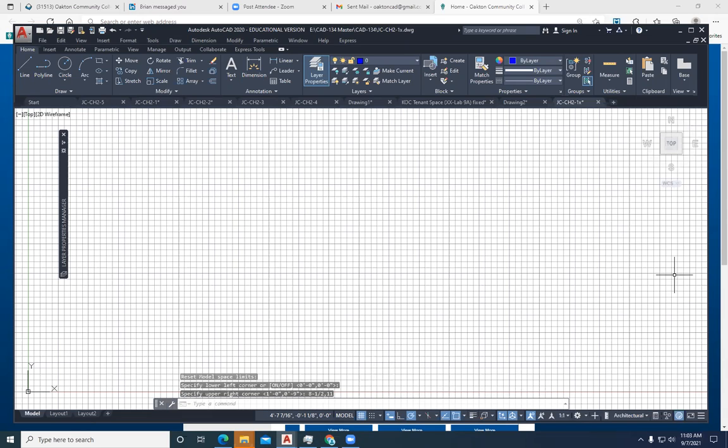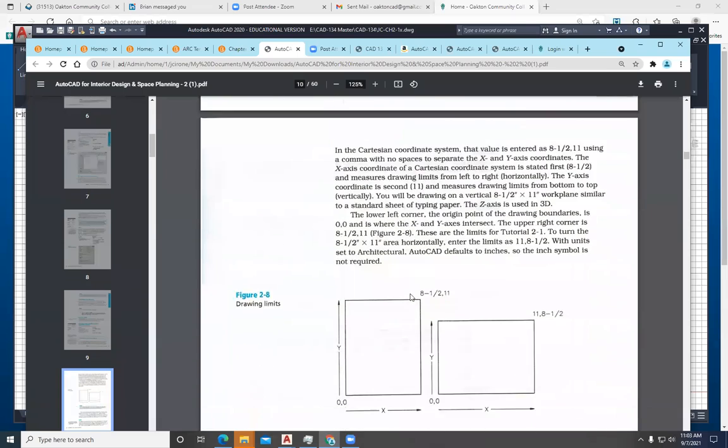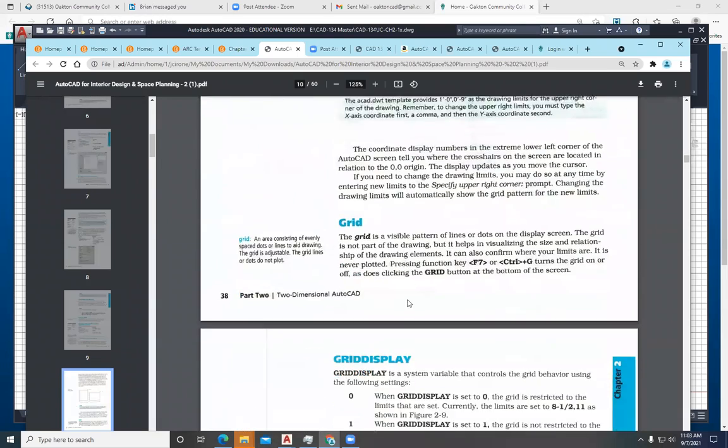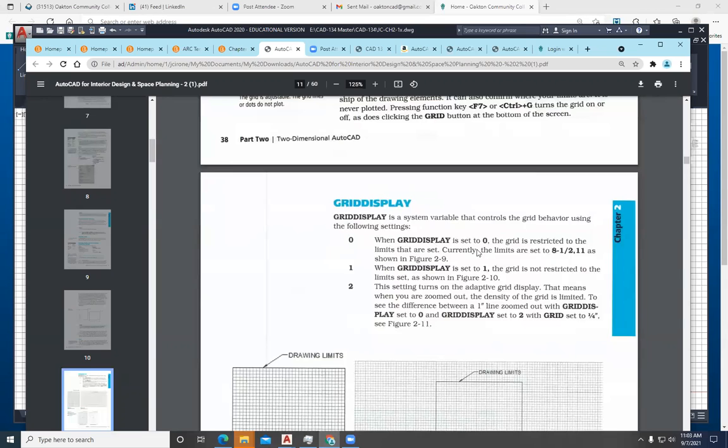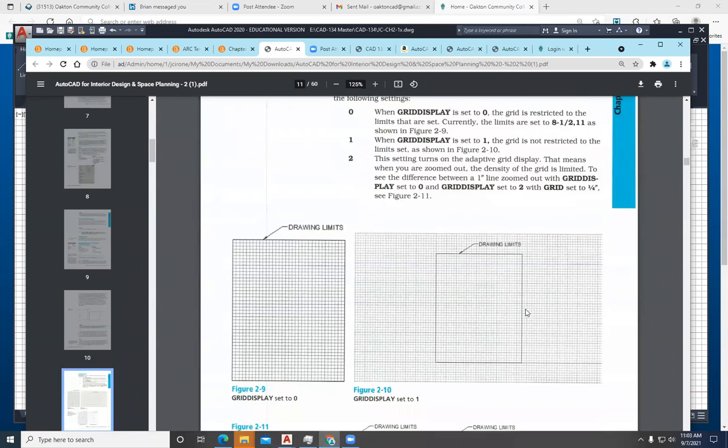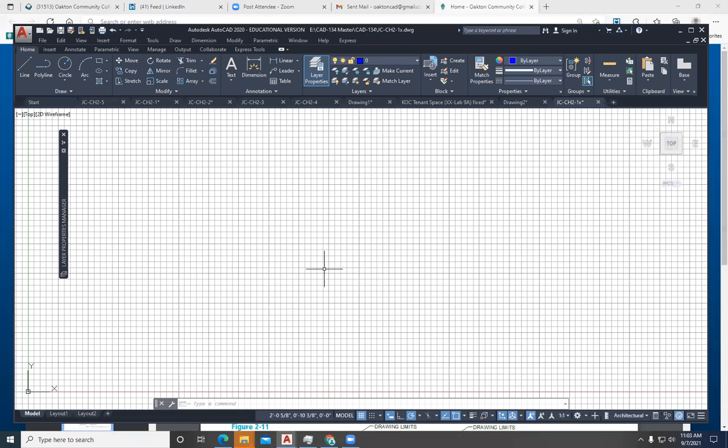And then what it has, this thing is, let's see, display the grid within the area. It's called grid display. And so grid display settings will change it from unlimited to within the grid area. So when I go to grid display, GRID, it'll be smart enough to give me all the commands that start with grid. And so I say grid display, and I change it from 3 to 0.